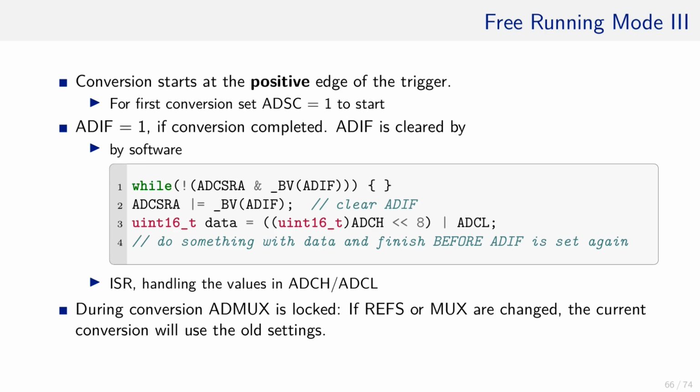Also note, and that error is easily done: we have to read 10 bits from ADCH and ADCL. Therefore, the ADCH value needs to be cast to a 16-bit integer first before shifting the high byte by 8 bits. Otherwise, you shift out the 8 bits of the 8-bit unsigned integer of ADCH, which results in the value that is stored in ADCL only, without bits 9 and 10.